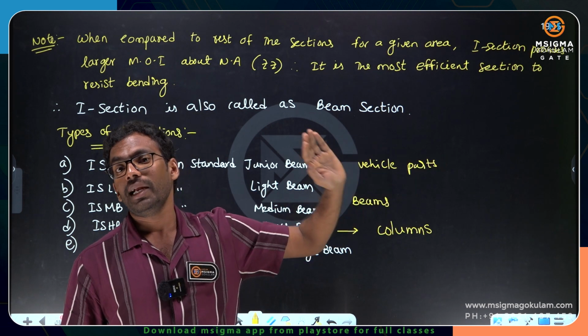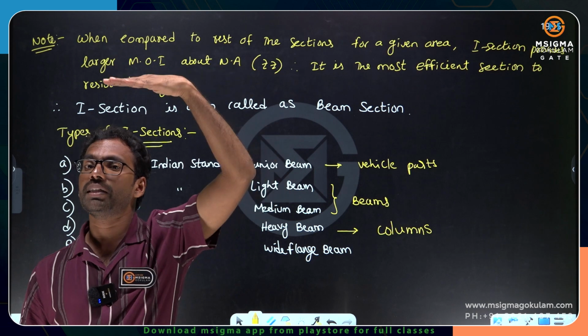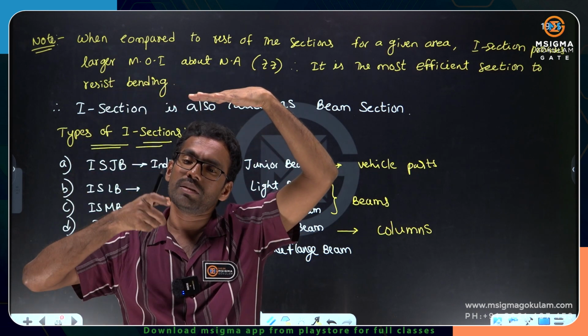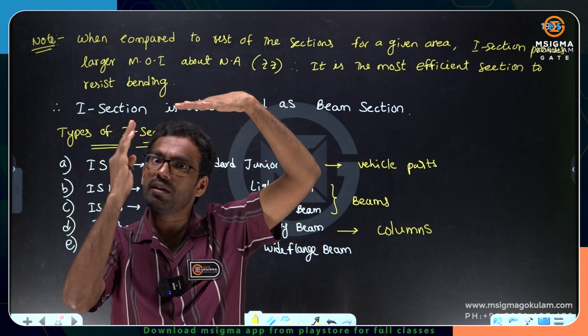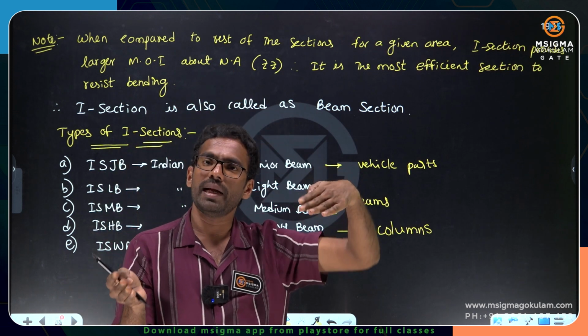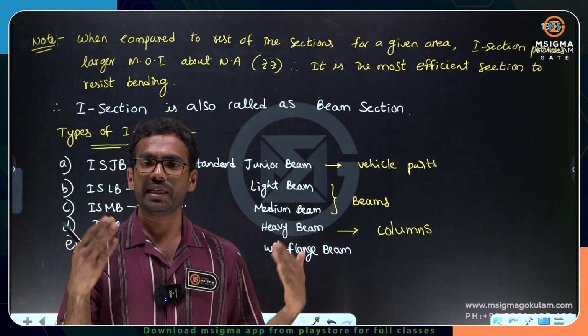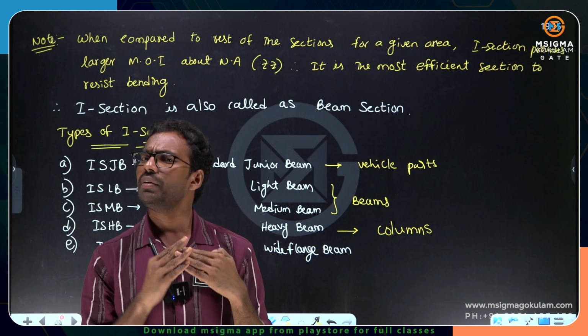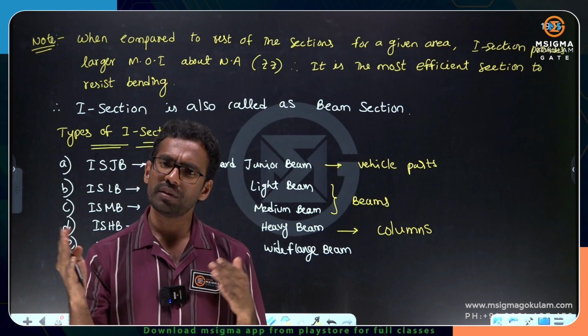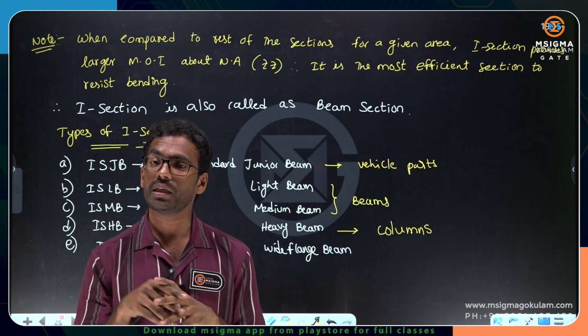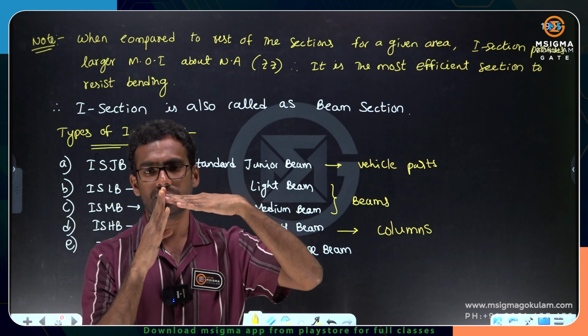But connecting the best beam section with the best column section is not possible. That is why, sometimes, even though some ideal things exist, because of connectivity issues and practical problems, we cannot go for ideal members. We go for relatively good members because of the limitations of connections.